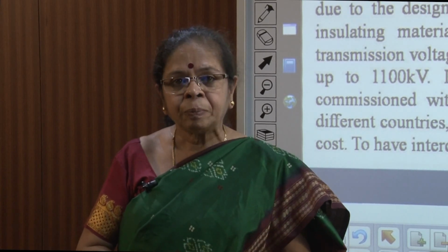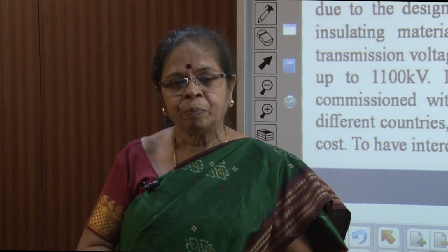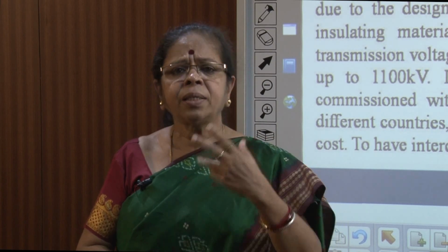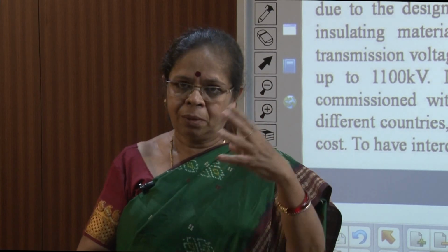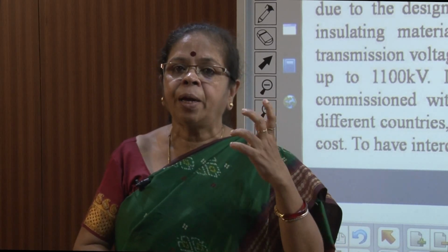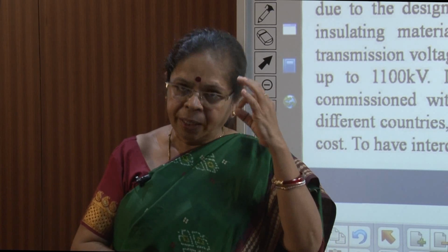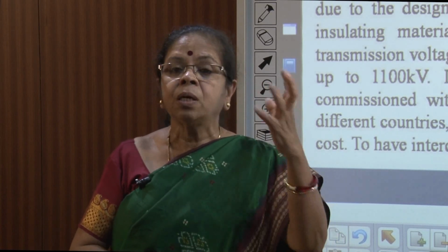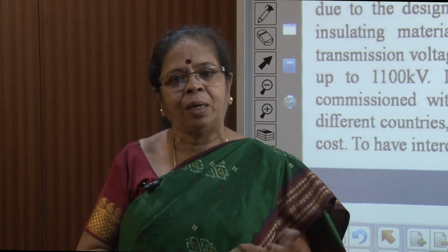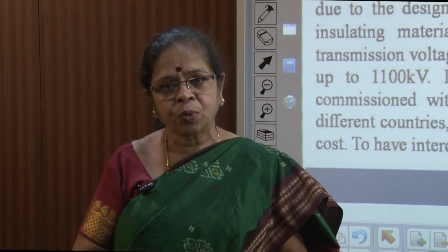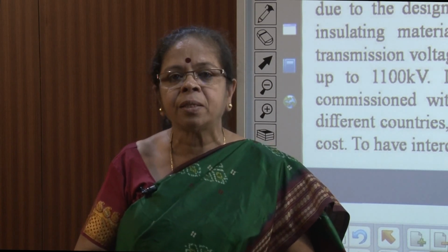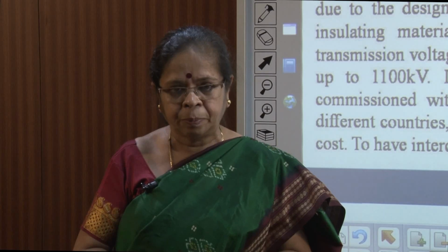Whereas in AC, I have the transformer, I can step up to very high levels and transmit the power at the high level. Okay? So, once I transmit power at higher voltages, automatically my current flowing through the lines will reduce, my losses will reduce, my voltage drop will reduce, my efficiency will increase, and there are so many advantages. So, this is one single reason why AC systems became very, very popular.